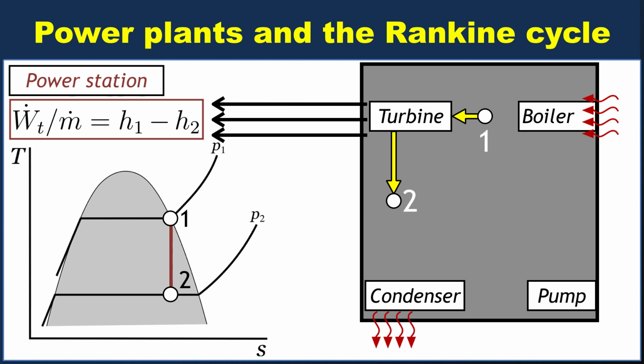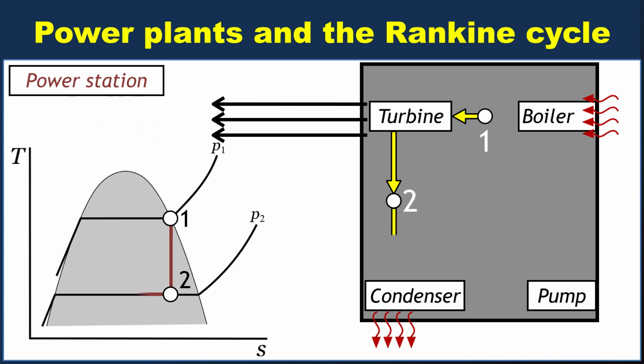Okay, so now we'll go through the condenser to get to state 3. So we do that, and we're going to go down through the condenser on the right. We're going from the right side to the left side of the TS diagram, so that tells us that indeed heat energy was transferred away from our system, which is consistent with the little wavy arrows under the condenser, right? You remember, area on a TS plot is heat exchange.